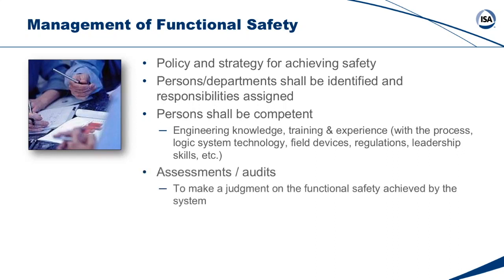Periodic audits need to be done to make sure you're actually doing what you said you've been doing, and there needs to be an assessment by a qualified team to make sure that what you're doing is adequate, that your SIL selections are being done properly, that your testing procedures are actually thorough, and the testing actually has written procedures on how to do it, and records are being kept. And that assessment team needs to have a senior, competent person not involved with the project, because the project team members won't see or admit to their own mistakes. And a senior, competent person who has the authority to stop the project from proceeding.